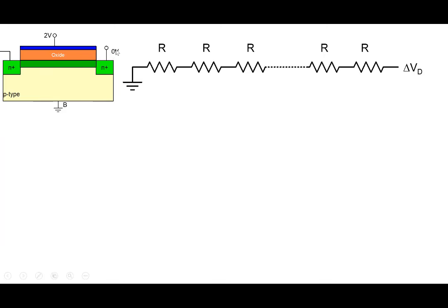When you have very low voltage or 0 voltage applied to the drain, then the channel is uniform. And when the channel is uniform, you can think of it being made up of a set of distributed resistors like this. If you change the drain voltage by a certain amount, delta VD, let's say I increase it by 0.5, it will distribute equally over all of these resistors. A fraction of the applied voltage will appear across this R here, and the current would increase.